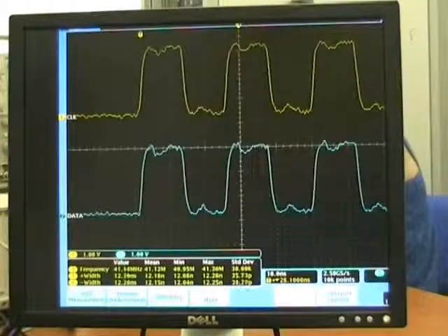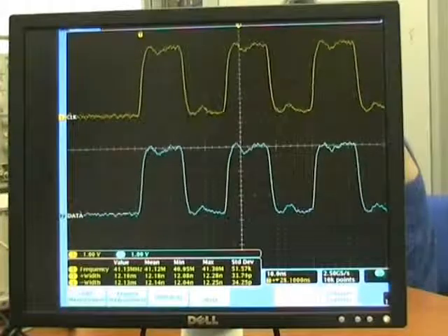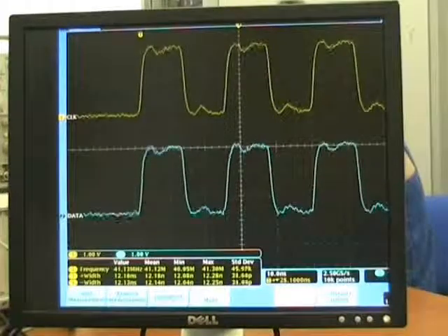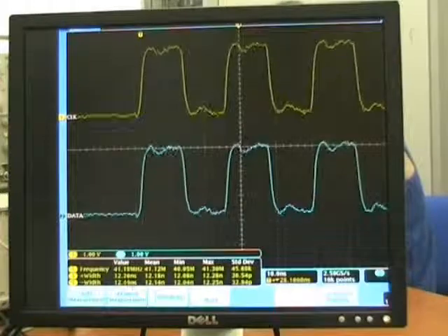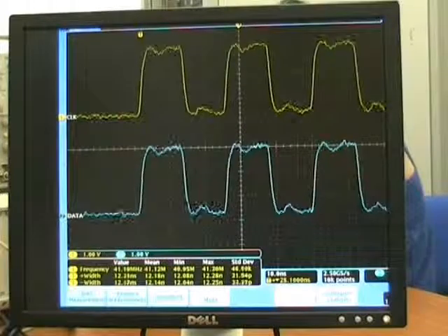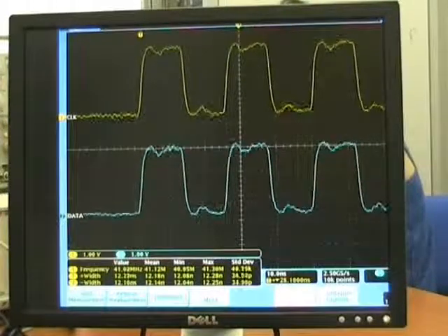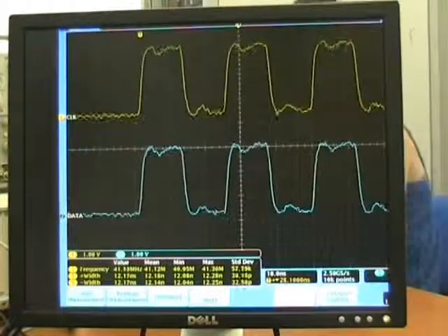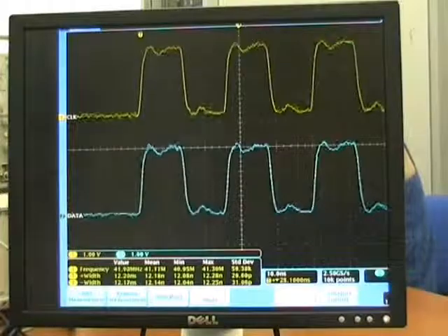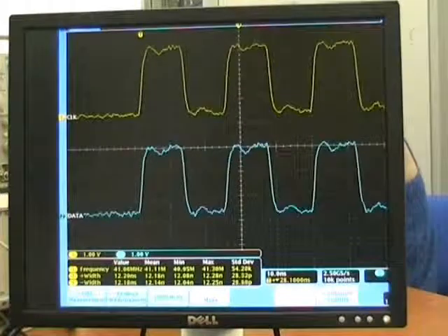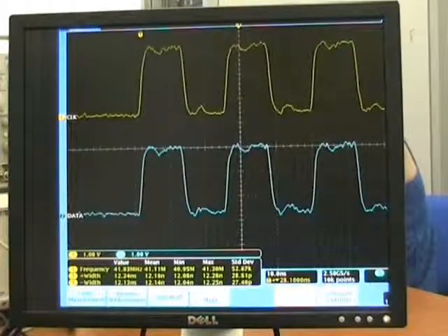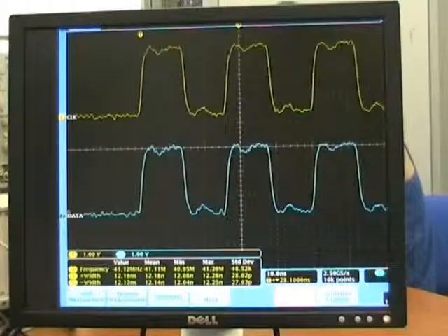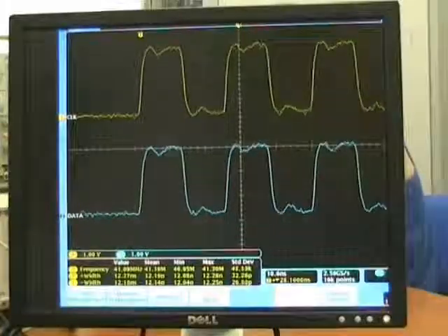This screen shows the actual output of the signal on the oscilloscope. We can see that there are two channels of digital pattern data being displayed, channel 2 and channel 3. They are shown as the two curves on the screen. Now let's zoom into the measurement data to look at the frequency and the positive and negative pulse width of the signal. Note that previously in the software we programmed it to generate an 82 MHz digital pattern.